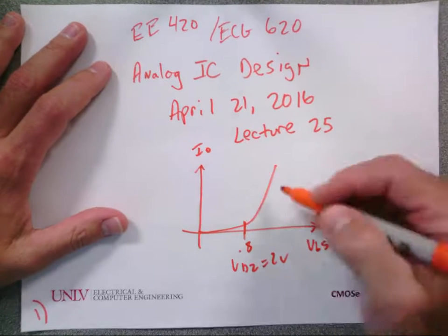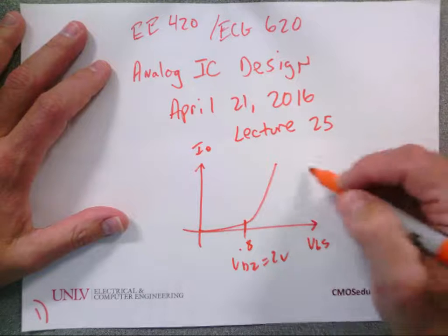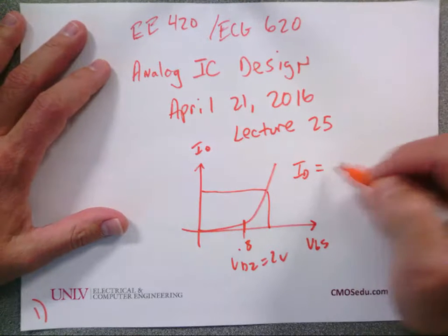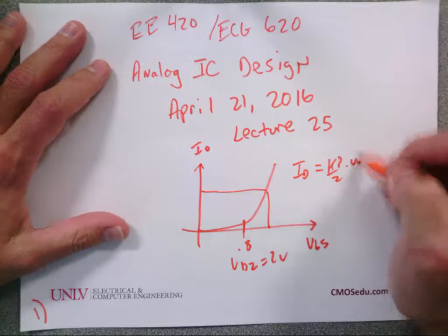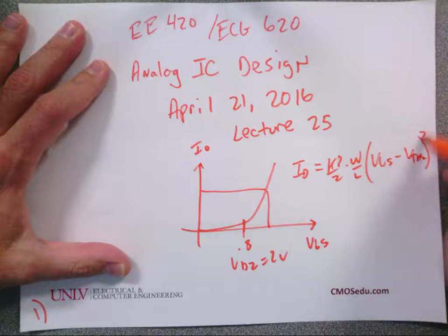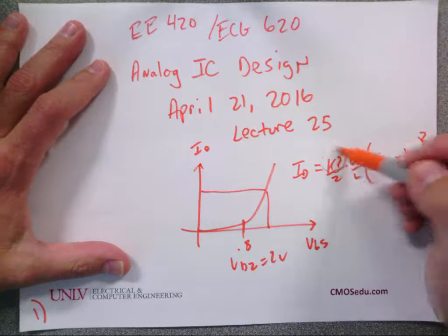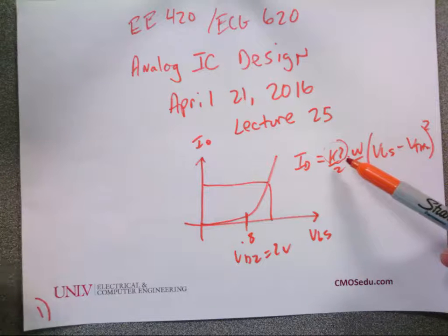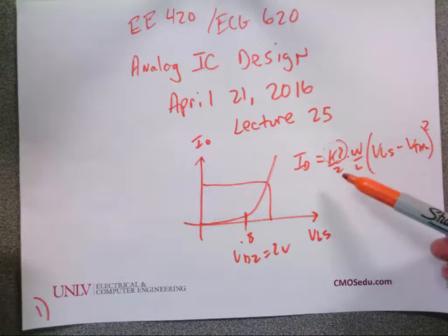Then you plug in for the specific size, whatever current you read at whatever VGS, and you get ID equals KP over 2 times W over L, VGS minus V threshold. The only thing you don't know is KP, and you can solve for that. But when you change it, because the mobility is going to change, it's not going to give you really reasonable values. That's why we didn't solve for KP when we did the 50 nanometer device.